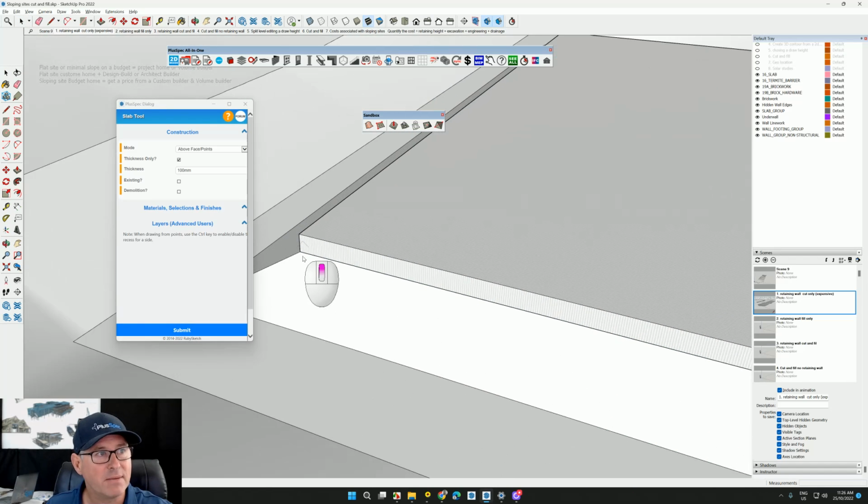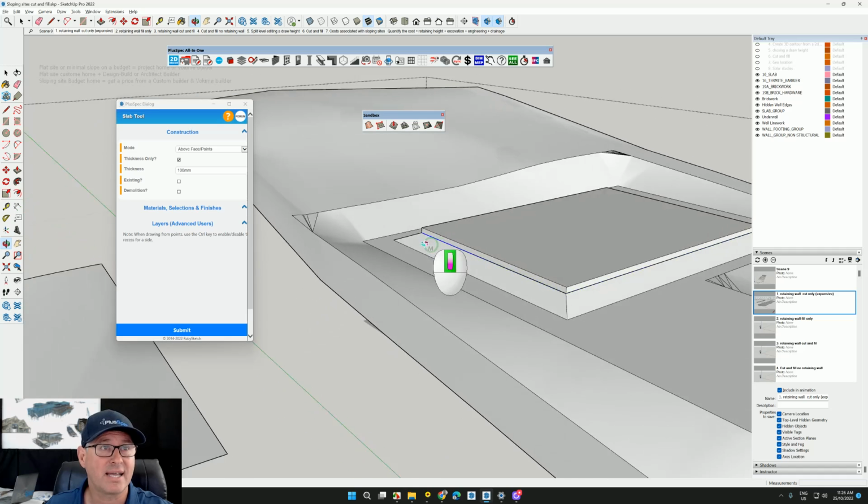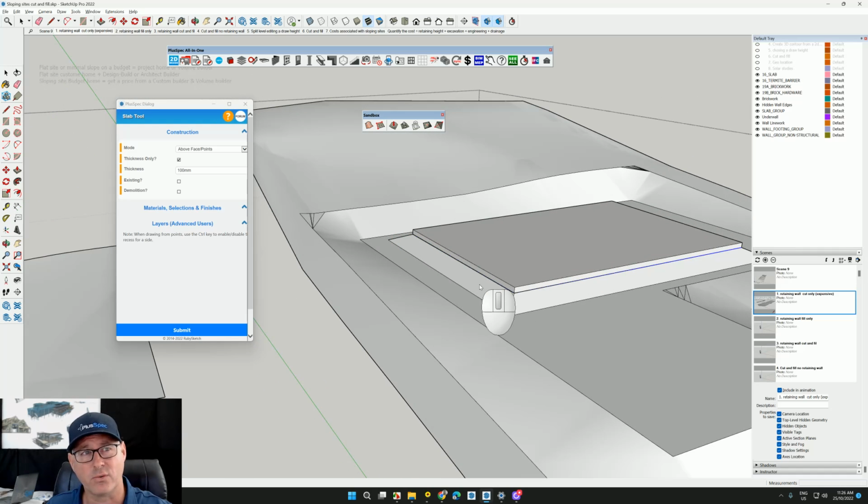Now there are minimum requirements in Australia. It's usually 2% that you need to slope away from the house from a certain amount of distance. All these things need to be taken into consideration when we're doing cut and fill.